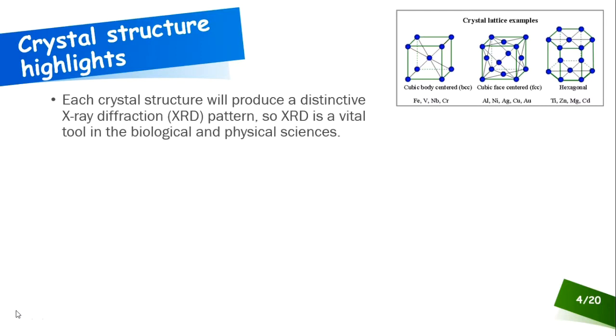So we grind the material into a powder, and then we put this powdered sample in the machine, and we bombard it with X-rays, and the X-rays deflect off at given angles and form a certain pattern on a photographic plate, and then you can look at that geometric pattern that's formed and tell what crystal structure your material has.